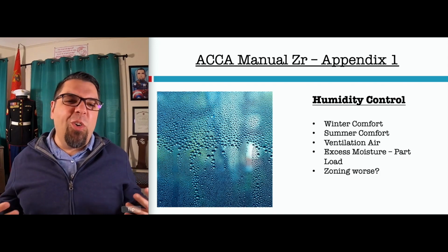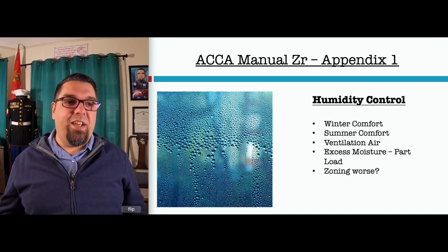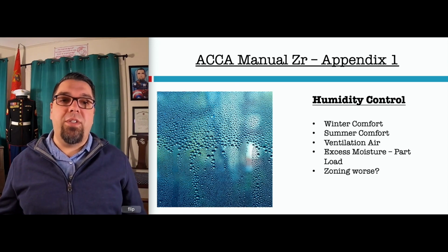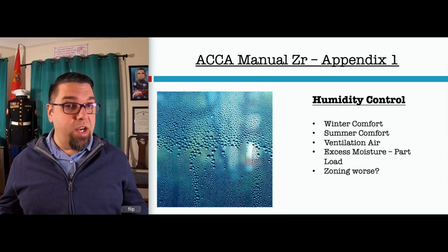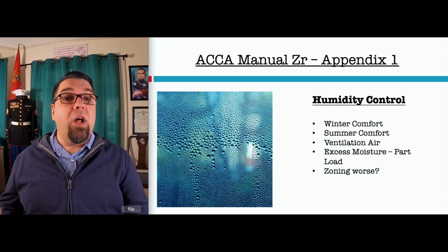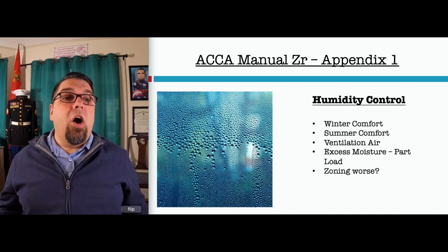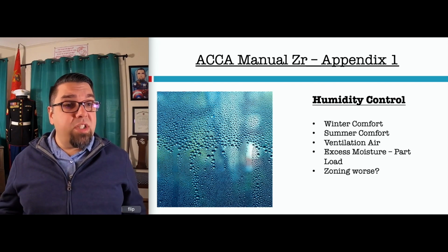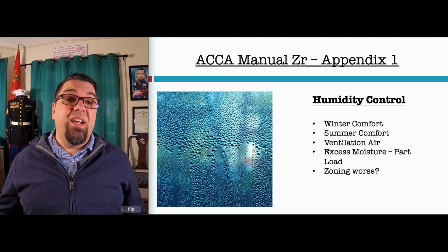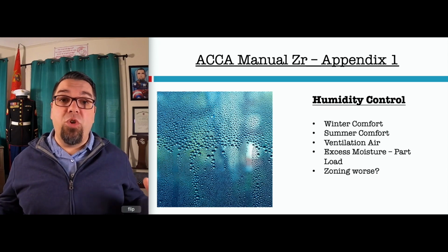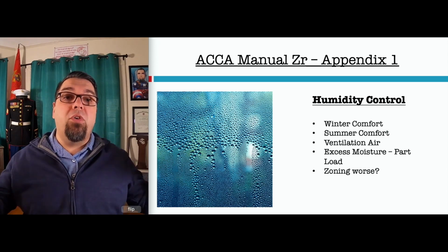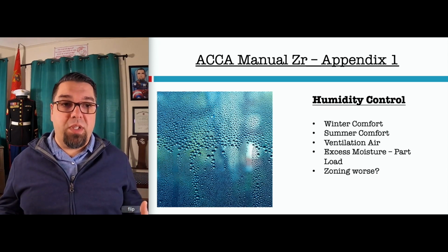And you're gonna feel cold and clammy because they're gonna keep turning that thermostat down. You gotta control the moisture in a house. So if you can't control it with just your air conditioning system, you put in a whole house dehumidifier to supplement it, right? Obviously we can control it sometimes with ventilation air. We're gonna dilute it. That's one possibility. But if you don't have balanced ventilation, we're gonna be pulling air in if we depressurize rooms in the house.